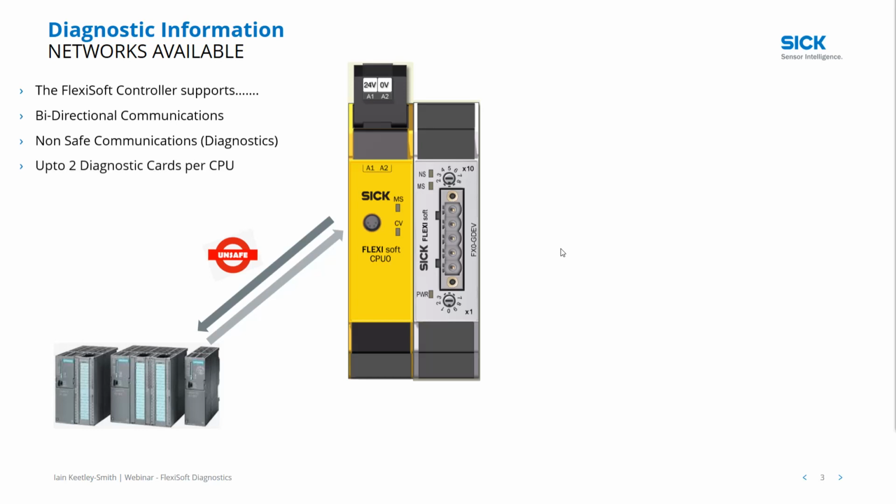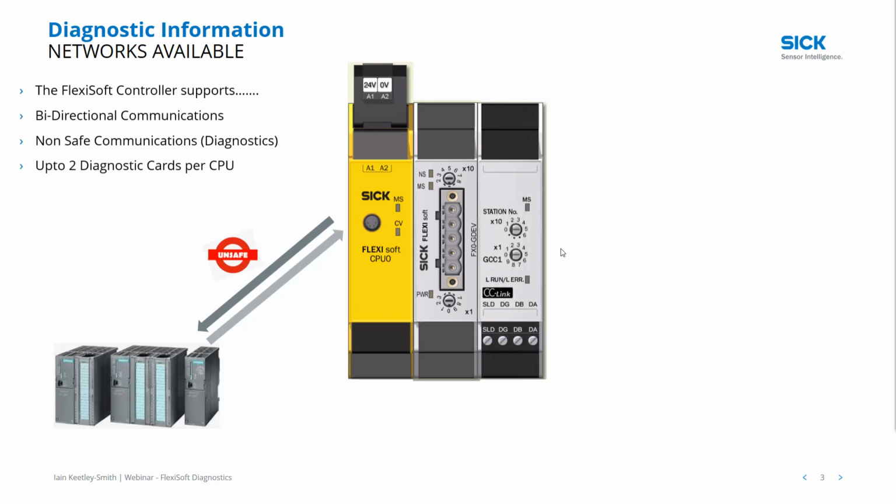We can also have up to 2 diagnostic cards per system. So now we can see in the image we've introduced a CC-Link card. So now we have a DeviceNet card and a CC-Link. So we can communicate on 2 different networks to 2 separate PLCs. There is a presentation or webinar that started the series called an Introduction to FlexiSoft, where we discussed the hardware that's available to you.